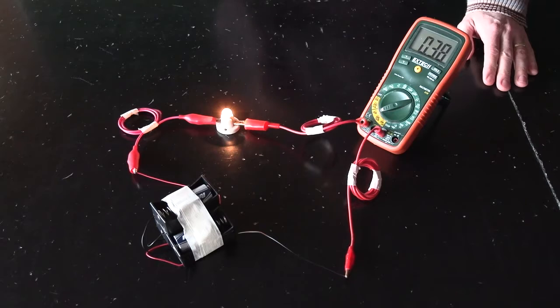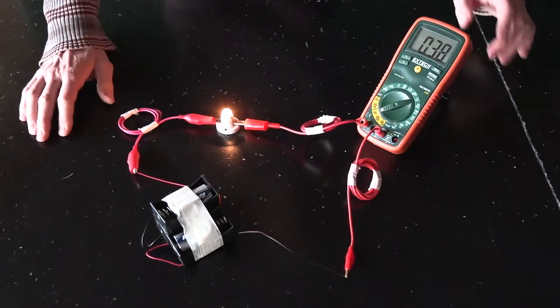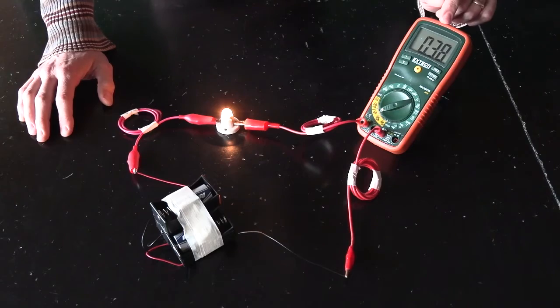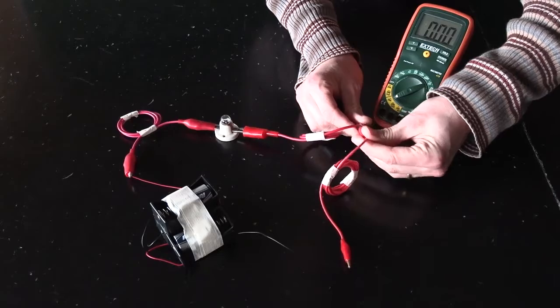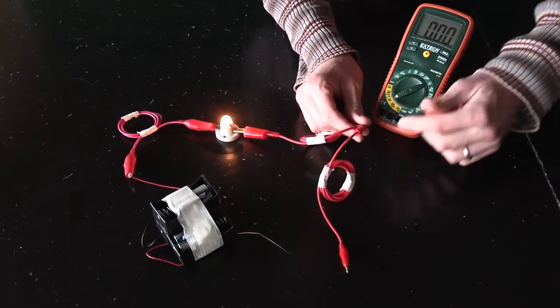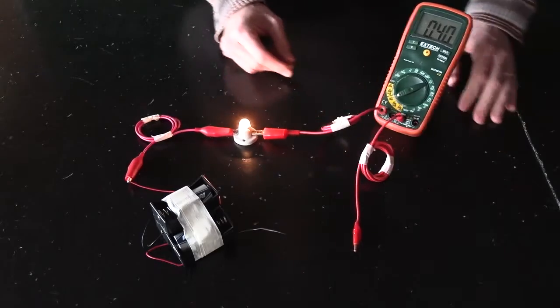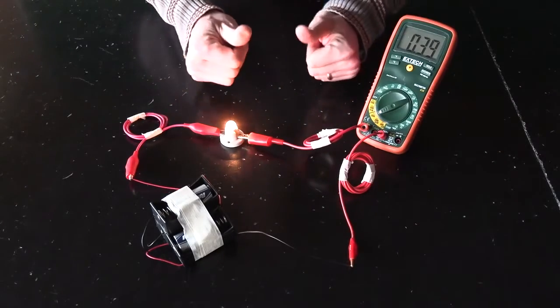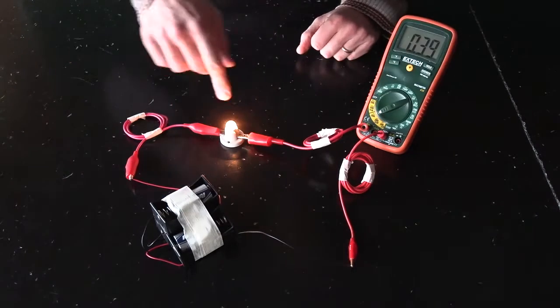But what we want to do is make an ammeter such that it doesn't restrict the current. Because if there was a high resistance here, without it, the bulb would be nice and bright. But if this had like 1,000 ohms, and then I go like this, suddenly the R_eq of this circuit would increase, more resistance, less current, and the bulb would be dimmer.